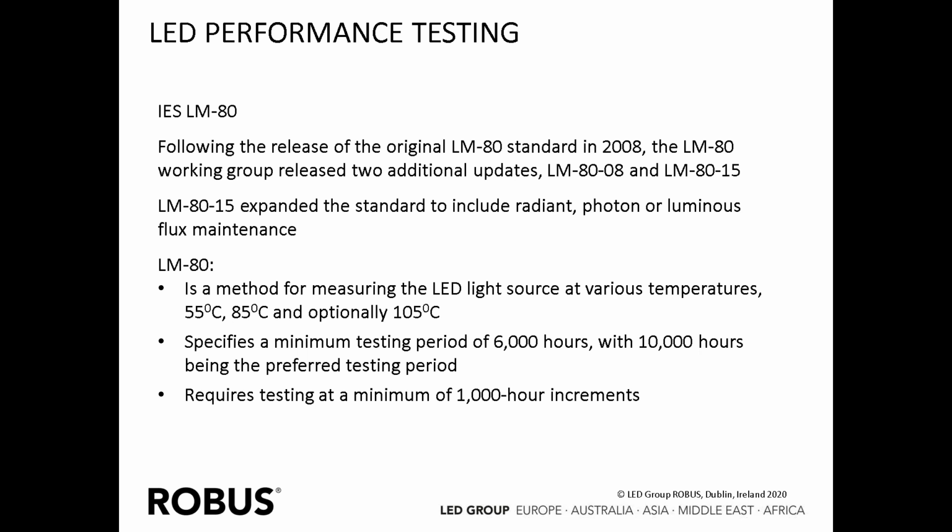It's a method for measuring the LED light source at various temperatures, and they're stipulated at 55 degrees, 85 degrees, and optionally at another manufacturer selected temperature, maybe 105 degrees, it does vary.